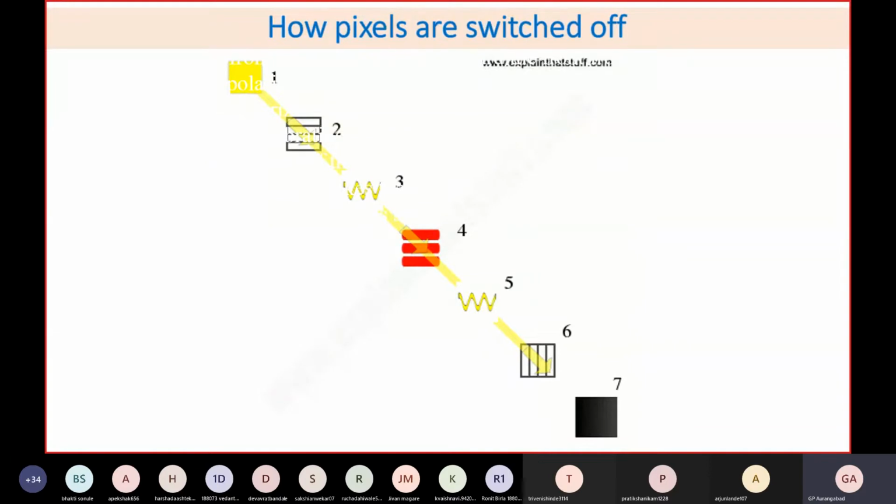You will find this horizontally polarized light coming from the light source, because the LCDs are untwisted due to the potential applied. The horizontally polarized light remains horizontally polarized, just like in 3 and 5. As the waves are horizontally polarized, when they pass through the vertical filter, the entire thing will be blocked and nothing will come out.